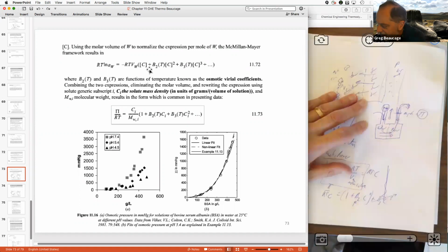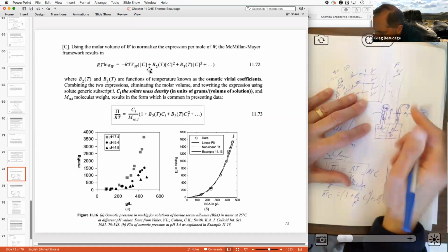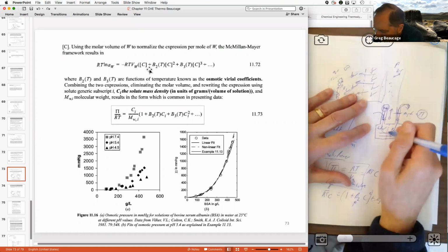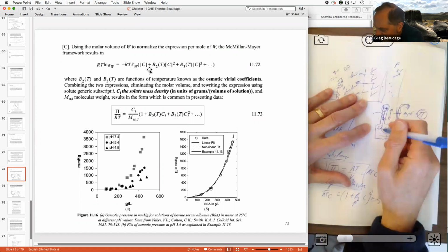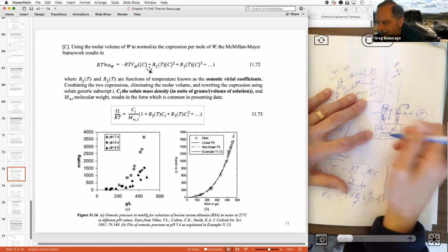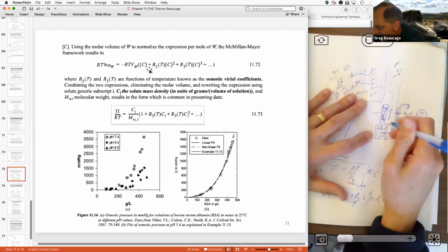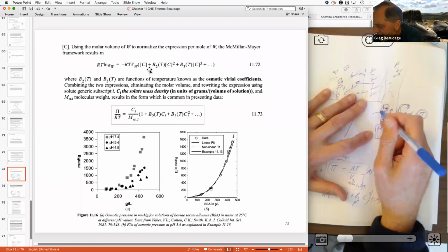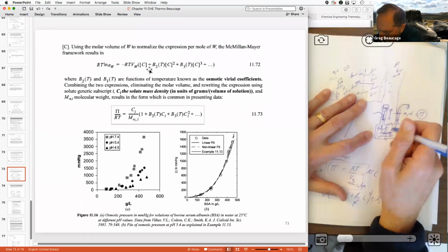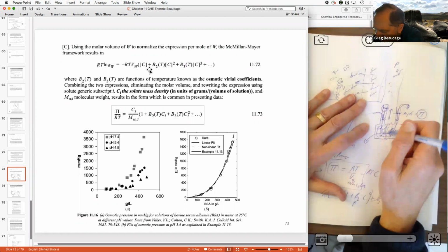So that's reverse osmosis. Osmosis is your skin shrinks. In reverse osmosis, you pressurize and pump the water out the other way, right? So anyway, here you're just pumping seawater, and then you're going to get a buildup of salt here, right? So membrane fouling is the main issue of this reverse osmosis. So how long can your membrane survive? So what you'll do is you'll have cycles. You'll be running this thing, run, run, run. Then you'll reverse to flush the membrane and dump the brine that you made. And then you'll pump more salt water in and then stop and dump the brine, right?